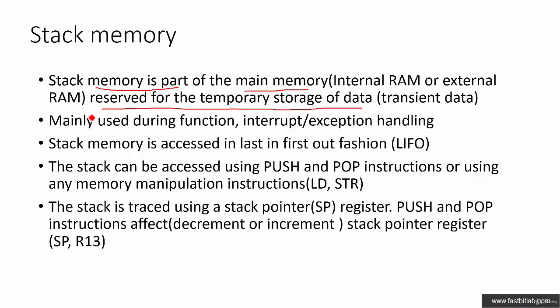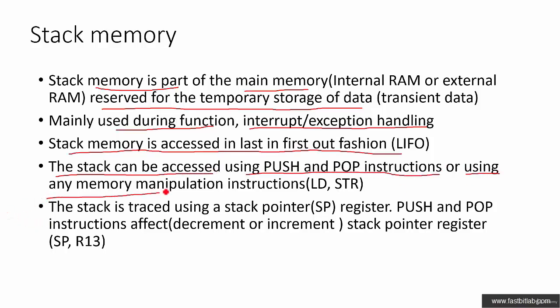Stack memory is mainly consumed during function or interrupt exception handling. Stack memory is accessed in a last in, first out fashion, that is LIFO fashion. The stack can be accessed using push and pop instructions or using any memory manipulation instructions such as load or store. Most processor architectures support a dedicated instruction such as push and pop in order to manipulate